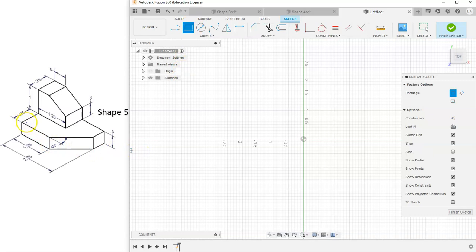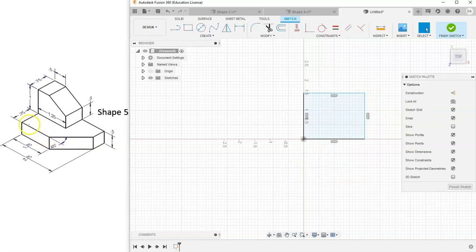And if I look at what's going on here, I can see there's a rectangle of this platform, and then coming out of it, extending out of it, is this slanted, weird sort of oblong shape. And so let's just grab our rectangle tool and just drag it out some distance and click. And let's add the dimensions after the fact. And so I'm going to right click and hit cancel. And so this is the rectangle that I just built all the way to the back here.